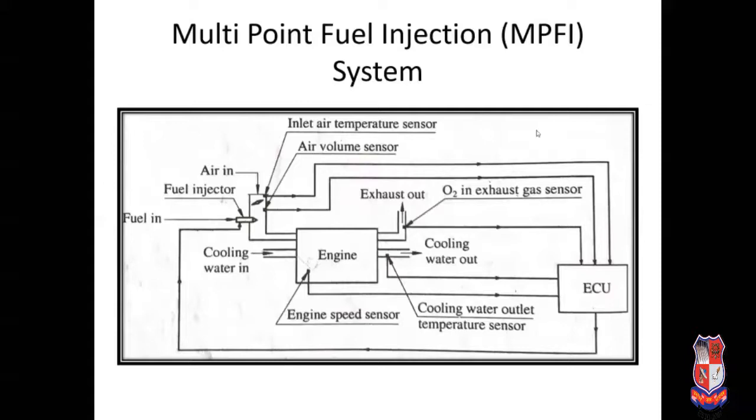So in the MPFI system there is a pump used. The function of the pump is to carry the fluid and to pressurize the fuel, and that fuel is supplied to the fuel injector, and the fuel injector transfers, or we can say injects, the fuel into the cylinder, or we can say the combustion chamber of the engine.